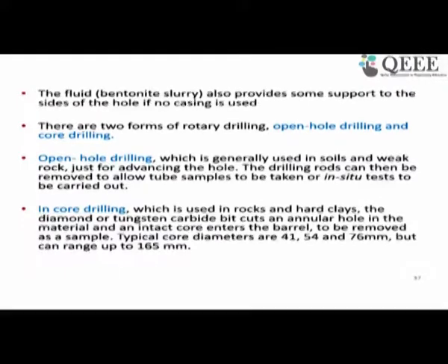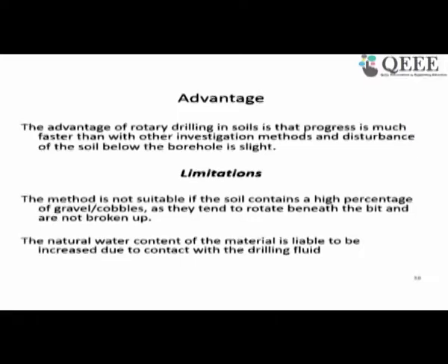Now the advantage with core drilling or rotary drilling is that it is very fast, as you can guess, and disturbance is also relatively low. But at the same time there are some limitations. If a high percentage of gravel and cobbles are there, then it is not very suitable. Also, the natural water content which is there in the soil may not be maintained.